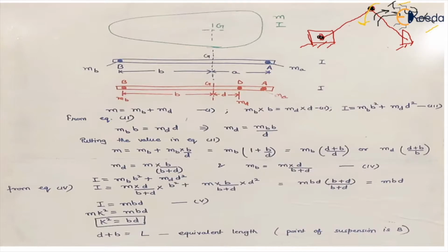We don't want the system to get affected while creating the dynamically equivalent system. So what we can do while creating this dynamically equivalent system is produce another couple. We produce a couple in such a way that this couple acts in the direction of alpha or the torque or omega, you can say in the direction of rotation of the crank, thus reducing the effect of the inertia torque because of the addition of masses at the crank pin. So the idea is simple.